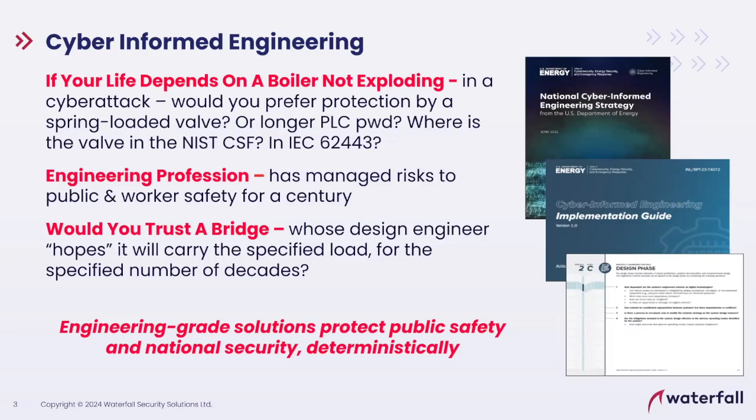When public safety is at risk, when the consequences are unacceptable, we expect bridge designs that will carry a specified load in a specified operating environment for a specified number of decades with a large margin for error. I asked a bridge designer who designs pedestrian bridges, how do you know how much load to calculate for the bridge? He says, well, it's easy. People are mostly water, and most of them are shorter than 2 meters. So calculate the weight of 2 meters of water, the width and the length of the bridge. That's your maximum load, he says. And then you multiply that load by 8 and you build the bridge to hold that load, because these are people. Failure of the bridge under load is unacceptable.